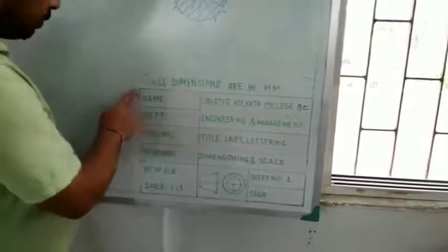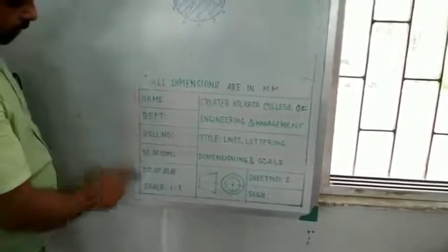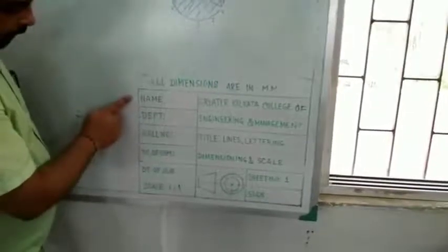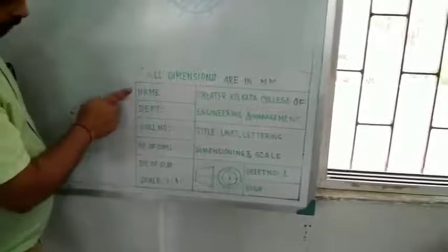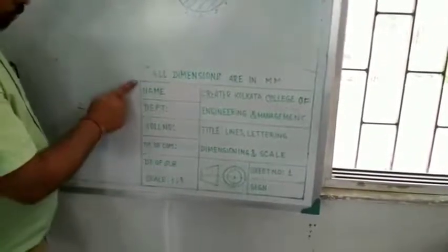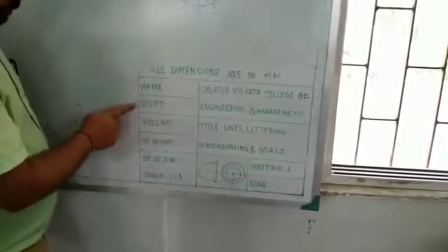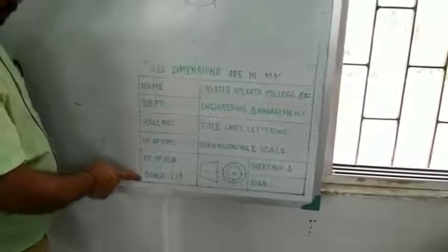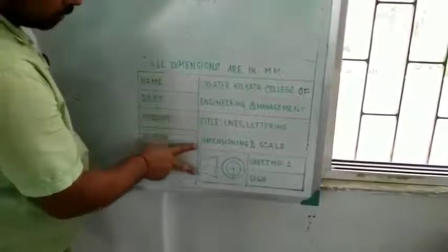Now you have to divide this section you can see over here into 6 equal divisions. So this total is 60. Each and every section will be of 10 millimeter, and this will be your 20 millimeter, 3 portions.